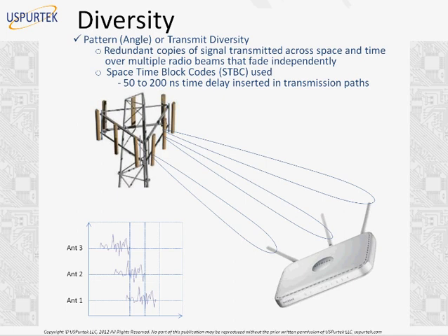Okay, so Veda Prabhu has a question. What about polarization diversity in circular polarization? Well, when you do circular polarization, you are actually transmitting the same signal over the vertical and the horizontal, right? So in that case, what happens? The same principle applies actually. So in circular polarization, it's automatically achieved. If you lose the vertical component, you still have the horizontal component on the same signal, right? So it's a very good question you have asked.